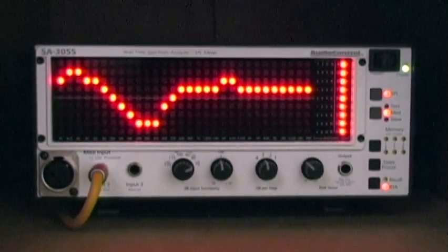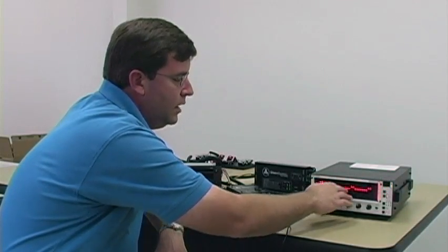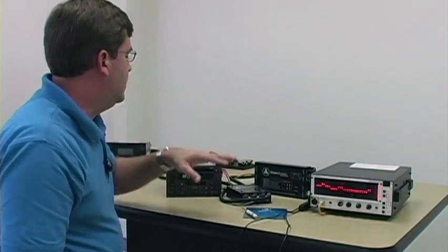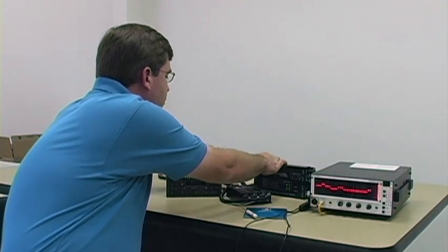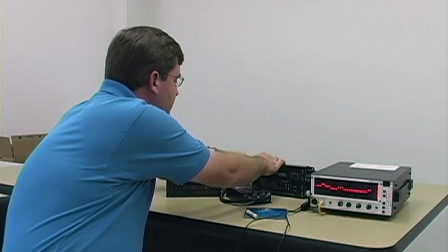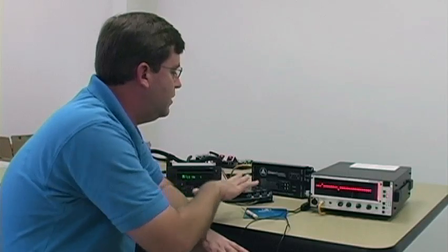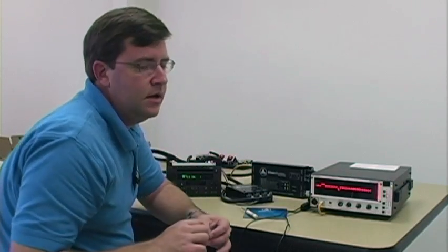Remember that had a very high pass frequency. It was actually staggered, but the CleanSweep was actually able to fill in that range and get it corrected relatively flat. So we started with a front high pass that was equalized, a rear high pass that was equalized, a sub signal that was equalized. We summed them together through the SSI, applied them into the DSP unit, and we're able to get very usable flat signals to use for our aftermarket system. And it was all done very quickly and very simply. The whole process of calibrating the SSI and calibrating the DSP should take no more than a couple of minutes once you've got all the connections made.